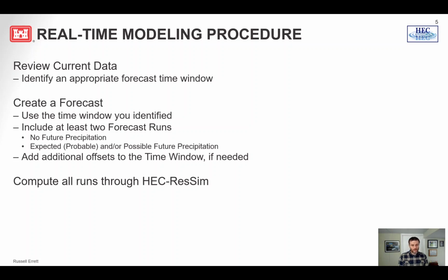So if your starting data point, and you're starting your simulation, doesn't have a data point far enough before the simulation to do that interpolation, you might get errors. So think about that when you're doing offsets. You might have to offset an extra day before you start a simulation, and even at the end, depending upon what kind of extract time series are dependent upon it as well.